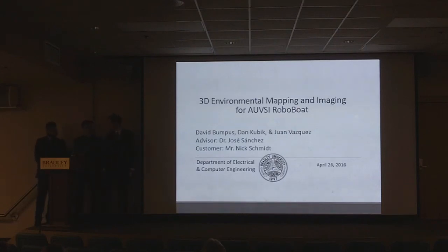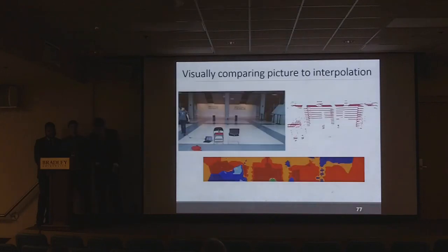So one potential thing that can be done, because it would be a non-uniform transformation between the LiDAR point cloud in 3 dimensions and 2 dimensions like you're saying, is to register the 2-dimensional image that is produced with another data set. If we could directly register the different elements of the image or the LiDAR point cloud with one another, that would enable us to have a non-uniform match between the 2 data sets, and that may help to reduce that error some.